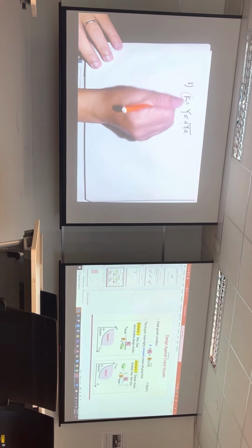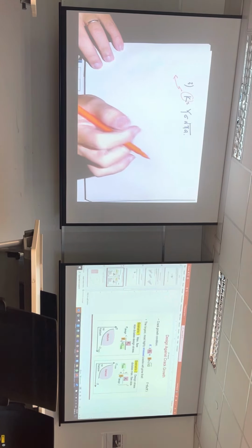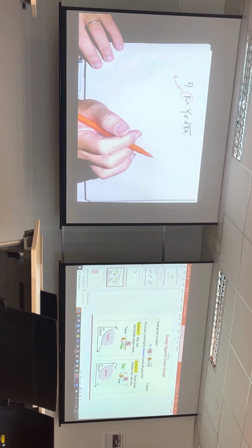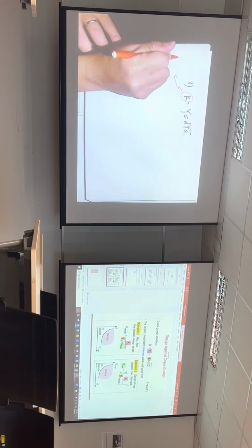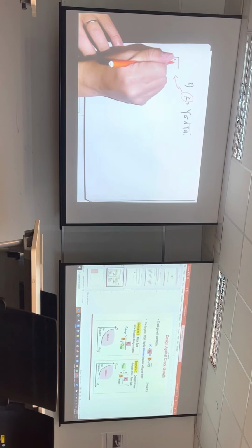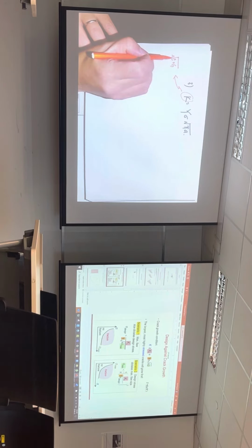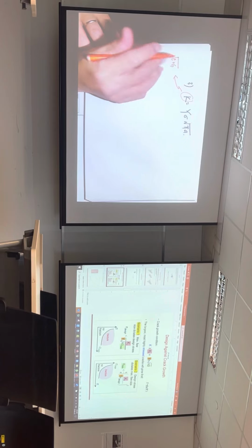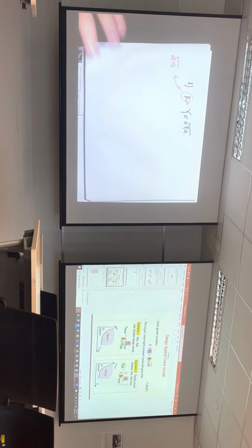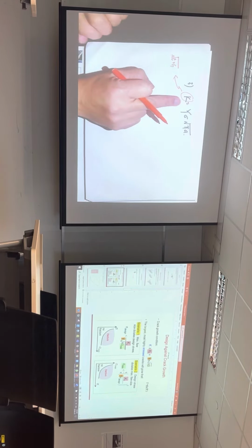So this K value, to a certain extent, is actually very closely related to the shear and the elastic modulus. If you look at the way that it's being derived, it's something to the idea of this one times your G. If E and G are the same, then this is actually in the ballpark figure of your elastic modulus. So basically you are trying to find the kind of average equivalent between the E and G. So this is your measurement of your pressure.